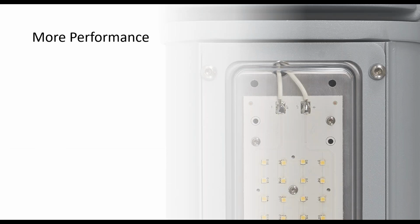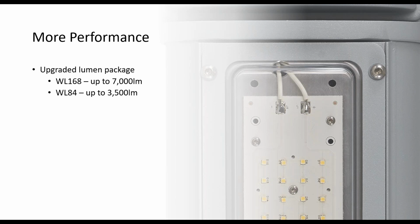Another big driver behind the project has been to maximize performance from the new linear. So we've addressed this on two fronts. One is to get more power out of the luminaires. So we have the WL168 variant, which is your traditional 4-foot or a 2x36 watt fluorescent replacement. That's now providing up to 7,000 lumens. The WL84 variant, your traditional 2-foot or your 2x18 watt replacement, is now at 3,500 lumens, which is a big jump from the Generation 1 version of the product.